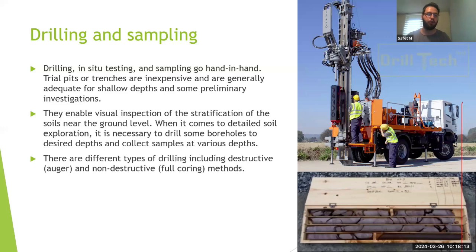The destructive method would be the auger method, which basically would damage your samples. You will get disturbed samples. It would work in some non-cohesive ground, such as sand or gravel. But if you are looking to have a core of clay, really soft material, or rocks, we are looking at non-destructive methods of drilling that give us the full core, as shown in the photo.